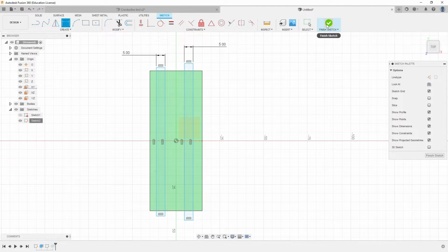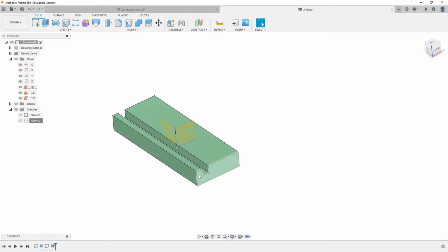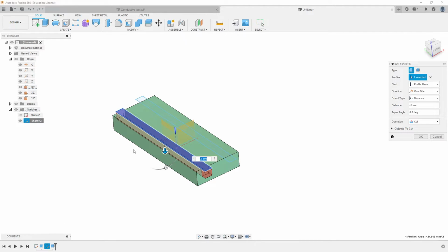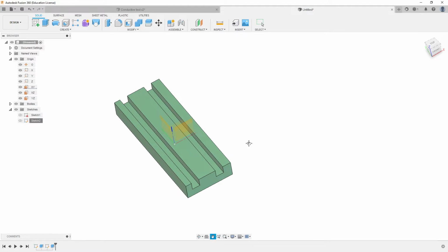If I were to exit out of Sketch right now, the extrude, by the way, only knows about that one, so I wouldn't do another extrude. I could just double click on the previous extrude and I can pick this other one right there. Okay. Again, please realize I know that you're watching this as a video and I'm talking pretty quickly. Pause it, rewind it, listen to what I'm saying, okay? So I hit OK with this, and now I've got both of those things there.